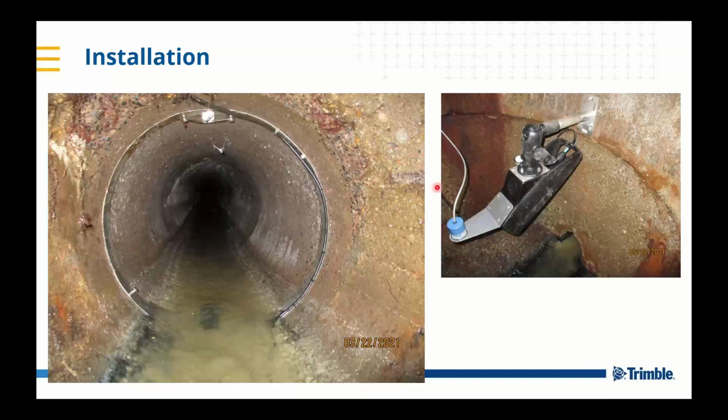And that's what our Raven-Eye looks like in a manhole, mounted backwards and reading negative velocity, because that's how we found the most effective way to get accurate velocity readings.